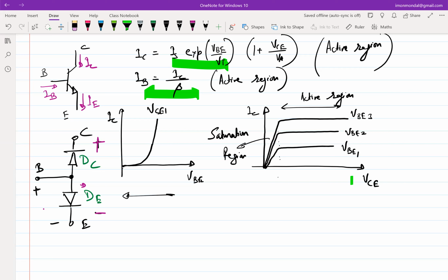So typically the cut-in voltage of a diode that we associate with is what, 0.65 volt, 0.7 volt or something. Again, we know that is an approximation. For a certain current range, we call that a cut-in voltage, but if the current range changes, that voltage can also change. But just like we did in the case of a diode at the very beginning of the course, you can say that this voltage is 0.65 volt if the diode is on and operational.